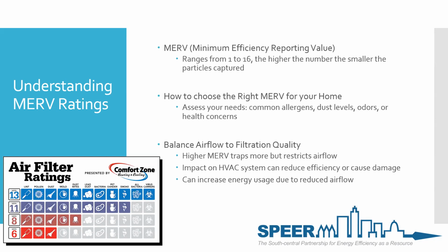I hope in the future, I know these systems are out there, but having a monitor, and we'll talk about some things that are in the future ahead in other slides, you'll be able to know what the static pressure is. And if you know the static pressure and it starts to rise or lower to extreme levels, it's time to change the filter.